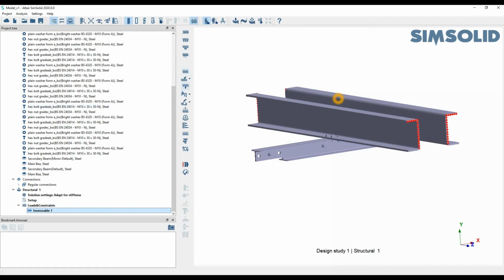You'll see for the next section down here, you have all of your different loads that you can apply. So you can apply pressures, force displacements, you can do gravity load. You can also specify inertia loads, remote loads as well. So just how we had remote supports, you can also have remote loads. So you can have a load acting on a part from a distance away, so it factors in all of the moments applicable to that surface. Obviously you can specify thermal loading, bearing loads, hydrostatic pressures, and any sort of distributed mass.